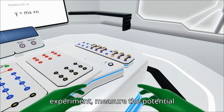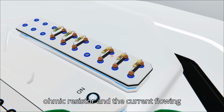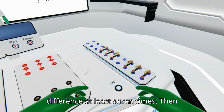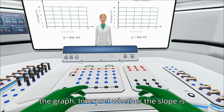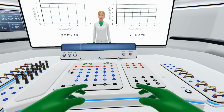In this experiment, measure the potential difference between the terminals of an ohmic resistor and the current flowing through the resistor. Measure these two quantities by changing the potential difference at least 7 times. Then plot the potential difference versus current graph. Then find the slope from the graph. Interpret whether the slope is equal to the electrical resistance.